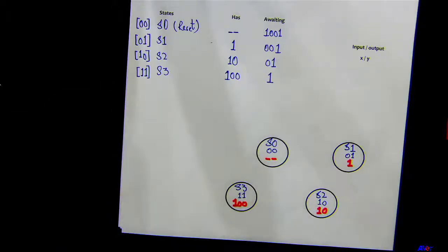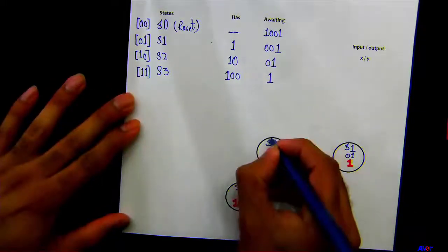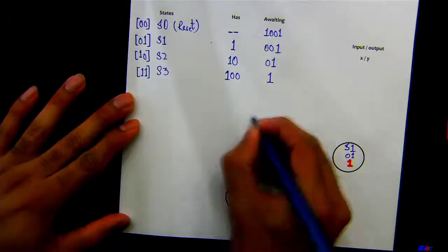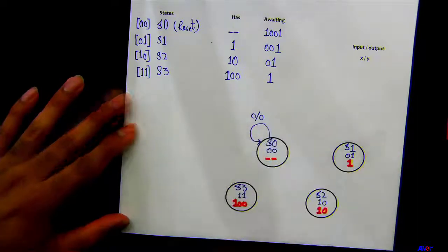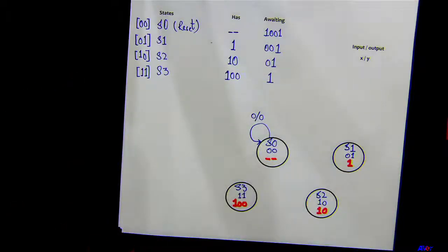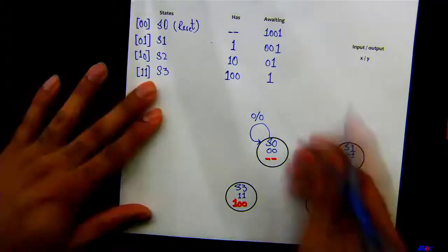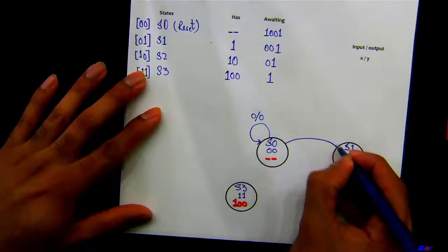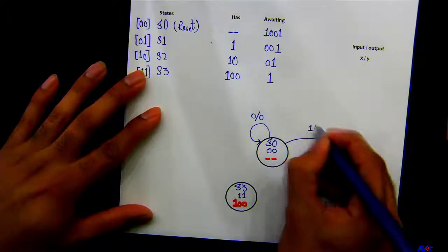Okay. So say the initial state is S0. 0 comes in. What is going to be the next state? Yes, it's going to stay there, right? So input is 0, output is going to be 0. The present state is S0. This is where it starts detecting. 1 comes in. What is going to be the next state? S1, correct? Okay. Input is 1, output is 0.